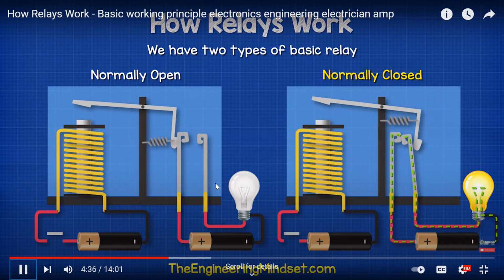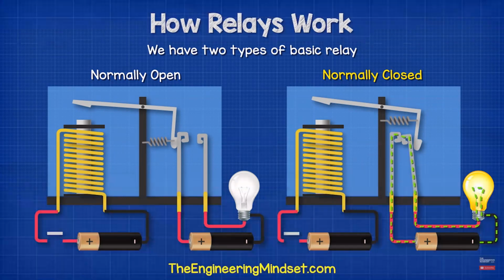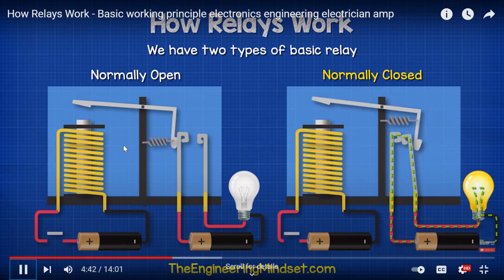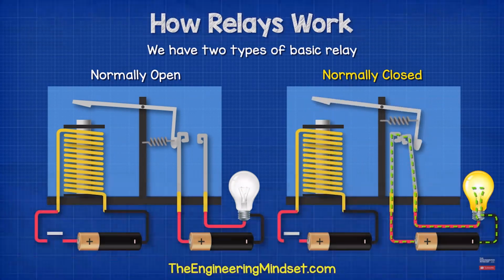And so the load is on. When the current is passed through the primary circuit, the electromagnetic field causes the armature to push away, which disconnects the contactor and breaks the circuit. This cuts the supply of electricity to the load.